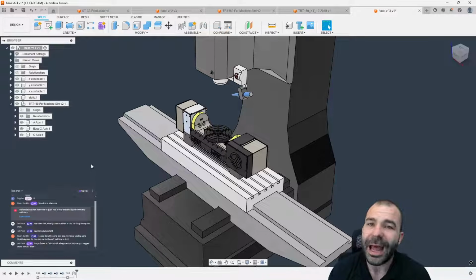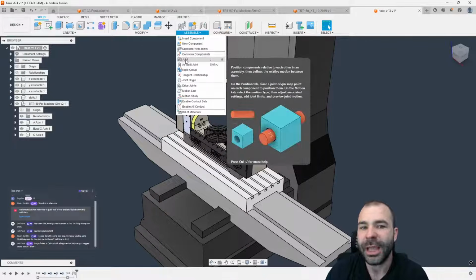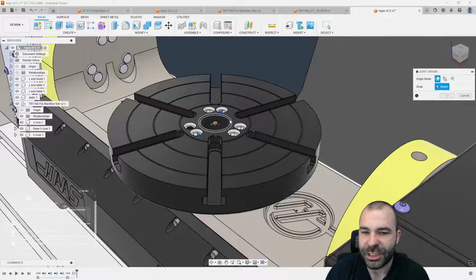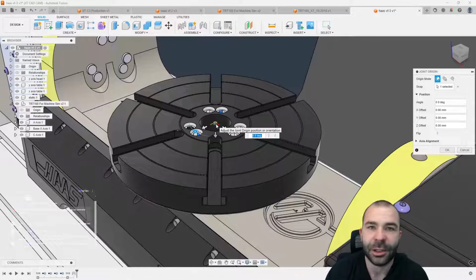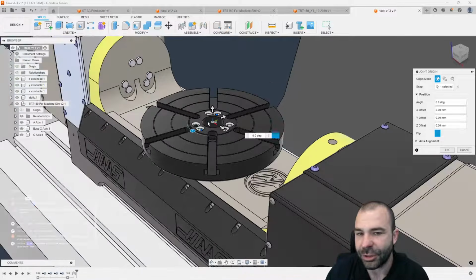Now, one thing I personally do, and this might be me, and you guys can tell me whether or not it's beneficial, is, depending on if you have tilted plane dynamic work offset G68.2, this is where I might, at the end of the day, create a joint origin. And the nice thing about the joint origin, as you guys could see, is I could put one down center on my platter. This might be my fixture location. Again, I'm going to flip it up and then, utilizing my color coding, make sure that we're orientated correctly.